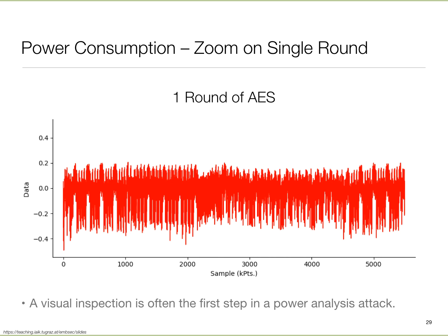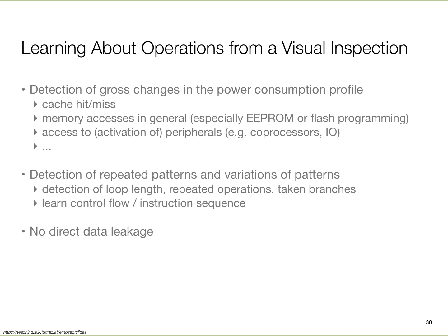And again, by examining the code, let's assume you have access to the code, you can begin to say something about what is happening out here, whether the key is 0, key is 1, those kind of things. And then this appears to be kind of the second phase. So looking at these traces, it seems like there's some structure to it, and they are not simply arbitrary. So the very first thing to do then is just visually inspect.